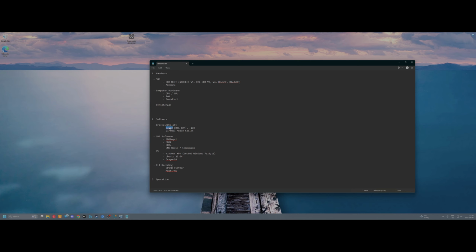It's not a plug-and-play device, so you need to sort of hold its hand through driver installation in order to get the SDR to communicate with the OS. It's very straightforward, and the website for any of these SDRs to purchase them will have information on how you can do this with Zadig, but we'll go through it here as well.